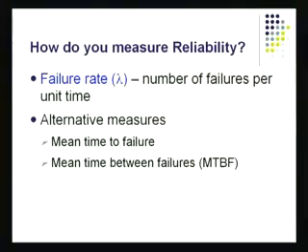How do we convey this notion of reliability? It's done always by number of failures over time. So this is called the failure rate, which I've called lambda here. Notice here the Greek letter lambda. This tells you the mean failure rate, which is the number of failures per unit time, which could be per year, and in some cases it could be per month, and hopefully it will be over a decade, or for large construction projects it could be over perhaps 100 years. How many failures would take place over 100 years? That's like something you'd like to keep your eye on. So failure rate is one great indicator of how good or bad reliability is.